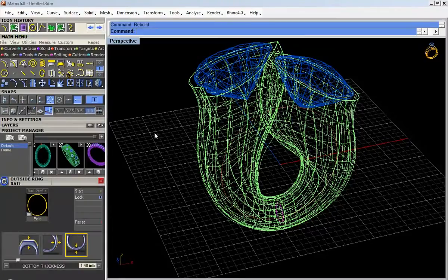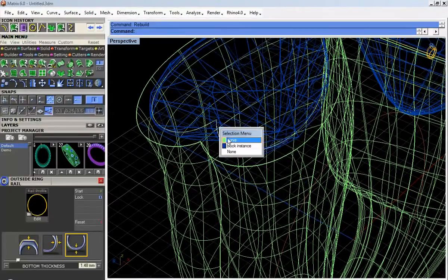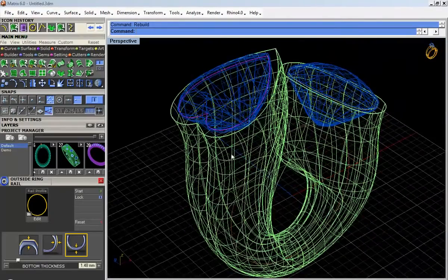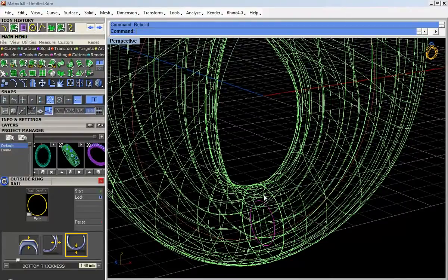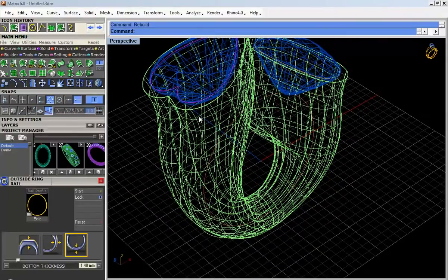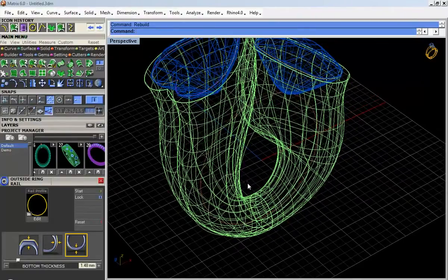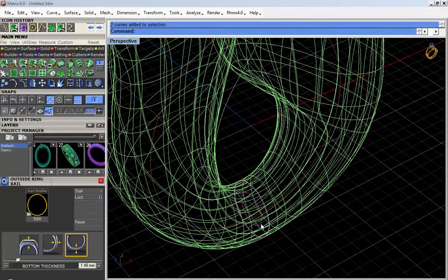I didn't understand that loop that you made inside, for what? Yeah, that's because we have one more curve over here, right? Inside, remember we did the offset inside, so that's why I took this one. I need one more curve for sweep 2 for this inside one, because I'm going to do sweep 2 again. So I made one more curve inside this one, so they maintain the thickness of 1 mm. I understand, right?